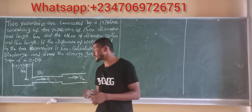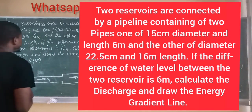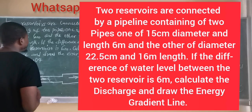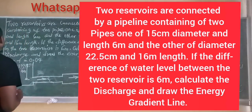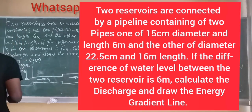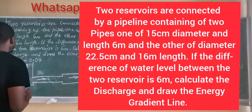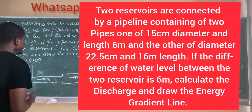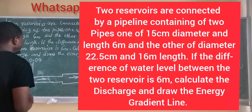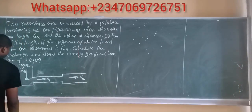All right, let's consider this question on the board. The question says two reservoirs are connected by a pipeline consisting of two pipes, one of 15 centimeter diameter and length 6 meters, and the other of diameter 22.5 centimeters and 16 meters length. If the difference of water level in the two reservoirs is 6 meters, calculate the discharge and draw the energy gradient line. All right, so we are given the pipe.